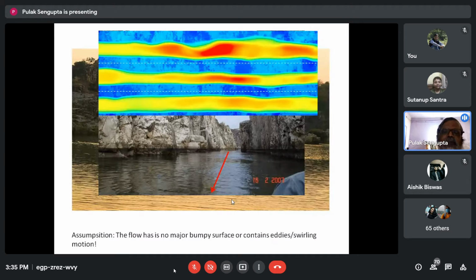Fine. Now, if I take a hypothetical cross section along the river direction of flow, numerically, it will be like that. It is layer after layer, layer after layer, and there is no mixing of layers. Red means the velocity is a little higher than this yellow, but otherwise it's almost parallel, and there is no mixing because there are no eddies across. So this is what one should expect. But again, I have made this just for your understanding, because I really do not know what the section would look like. But if I make this assumption, then possibly I can use this numerically computed diagram.